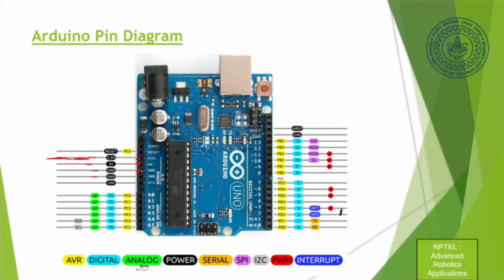Okay. Now this part is going to your PC or laptop. Okay. Now these are the other pins which are called analog in pins. You can see it is written here as ground power pins. Here it is written analog in pins. So A0, A1, A2, A3. So these are analog in pins. Okay. Now they can also be set as digital pins. So the color coding is different. So you need to set it, okay, as an analog pin or a digital pin.